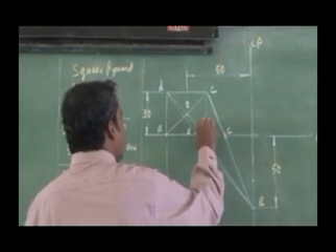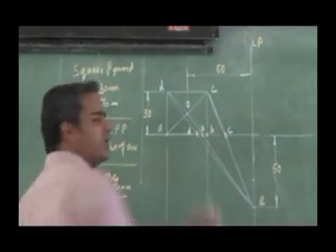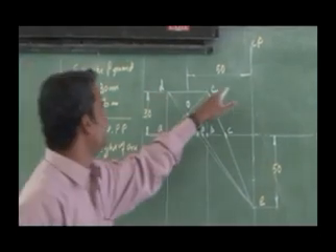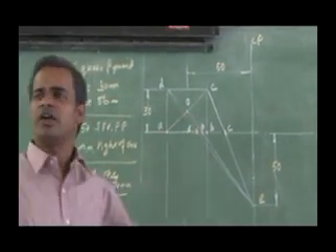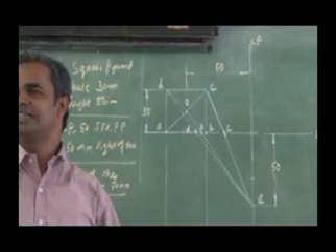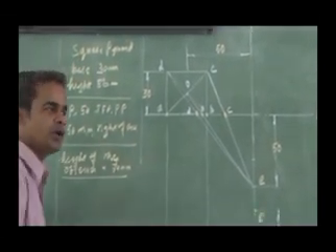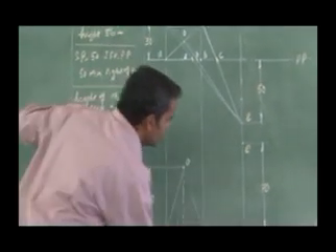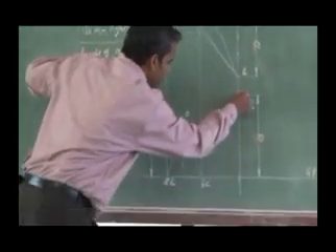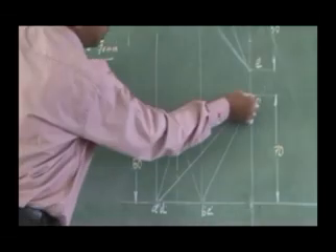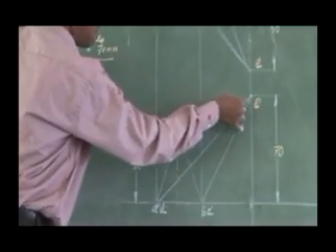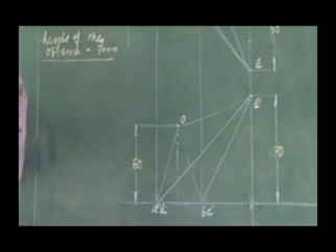Now, you have to get only three intercepts. That is D, C and O. A and B are on the same location because it touches the picture plane. Now you draw the visual ray line for your front view corners. Right. Then you take the apex. Right. Now you project these intercept locations.